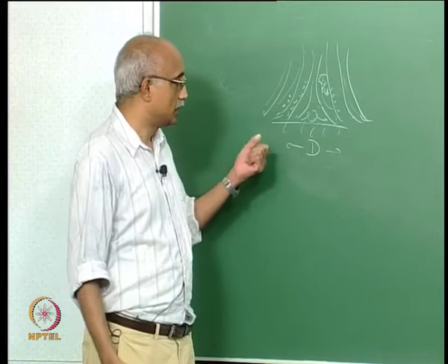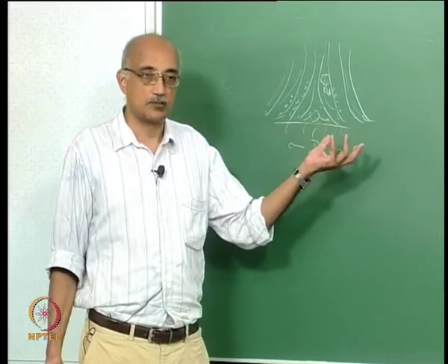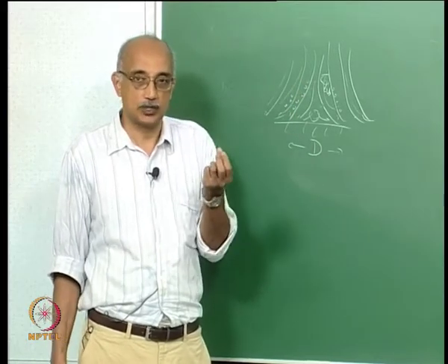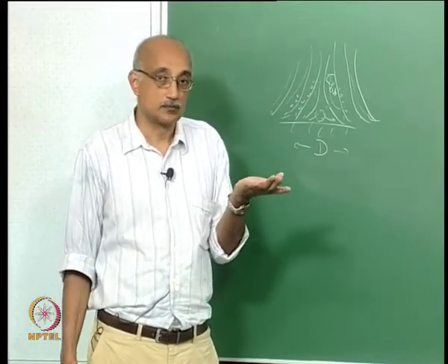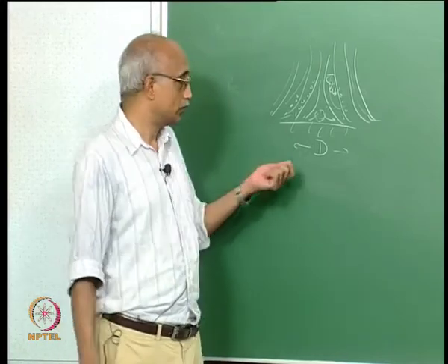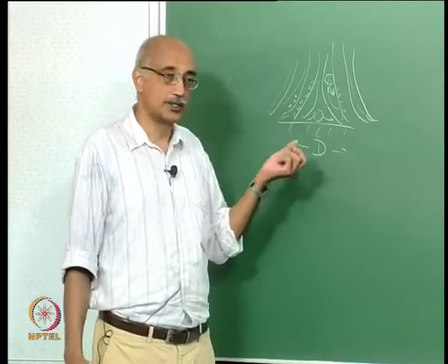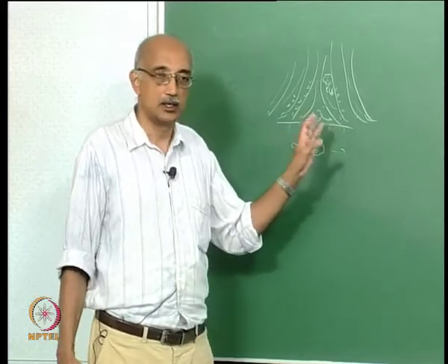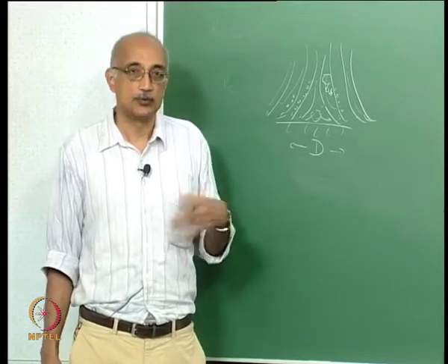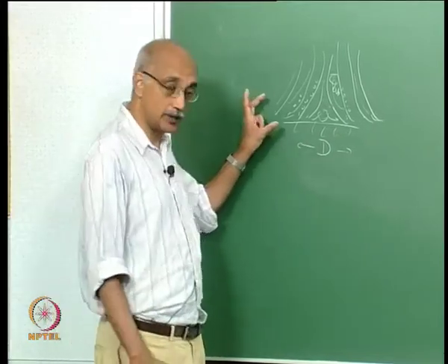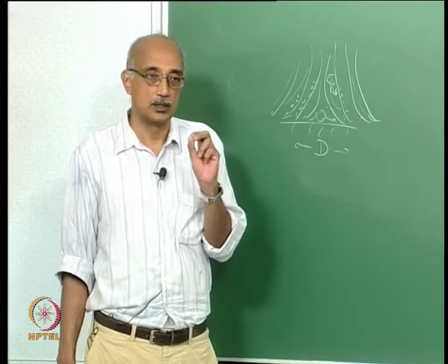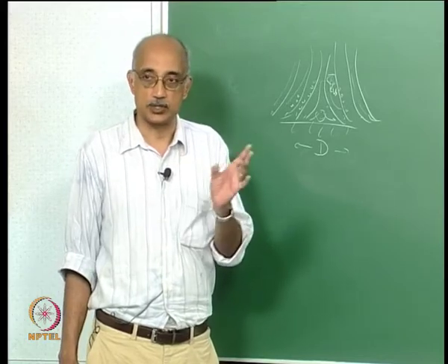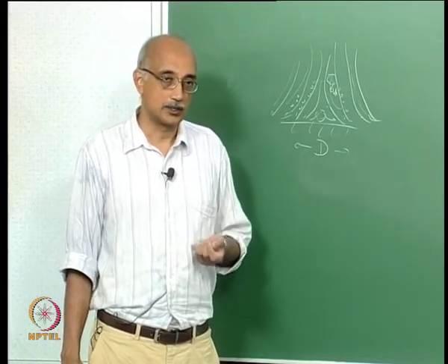So for example, you want to minimize collection of particles on the surface, so you eliminate all supermicron sized particles and substitute them with nano-sized particles. Is that good? Well, what's going to happen is all these nanoparticles are going to have very high diffusion rates, and so they are going to start again depositing on the surface by diffusional means. Or if there is a thermal gradient, again the finer the particle, the greater will be the effect of what's known as thermal diffusion or thermophoresis. That will also aid in the collection of particles.